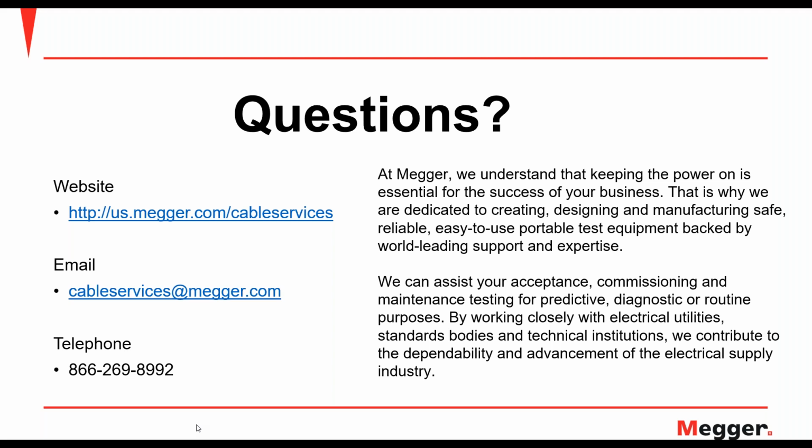All right, excellent. Next is over to Gallo. Gallo, how much time would it take to test a segment, considering the cable length and range? Well, if we are performing a VLF test, and assuming this is a new cable according to the standard recommendations, this will take about 60 minutes. And if this is an aged cable, then we probably perform a VLF test in 30 minutes.